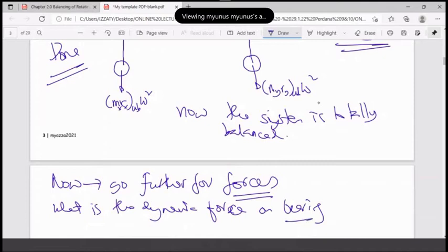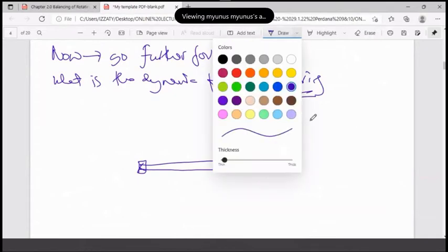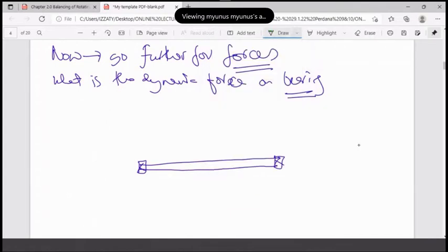So on bearing now, put the same problem. I want you to really understand this one, so the next thing will be very easy for you. You have a mass here just now, the unbalanced one. This one is also unbalanced, isn't it? If this is A and this is B, this is X and this is Y, the M you created just now is MR for A omega square, and the other one is MR for B omega square.